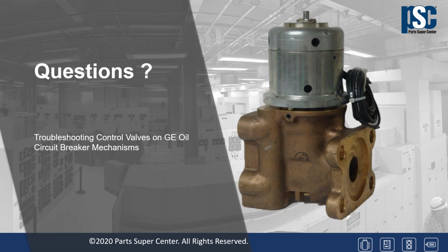Now, in terms of changing the timing of the breaker tripping, that is primarily done through the tail spring, which is usually at the end of the phase farthest from the mechanism if you have a 3-tank breaker, or if you have a single tank breaker, it would be directly opposite and farthest away from the mechanism cabinet. There are instructions on how to do that in the instruction book. So if the person who asked this question wants to give us the serial number of the instruction book, we'll make sure that we get you that.